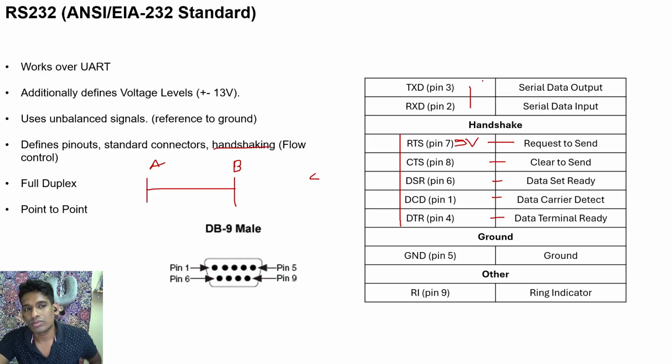Nowadays, RS232 will be used over some other higher level protocol or higher level application which takes care of all the handshaking. So there is no need of hardware handshaking. The higher level protocol which is used above RS232 will take care of the handshaking. So these pins are not required at all right now if you are using a higher level protocol.